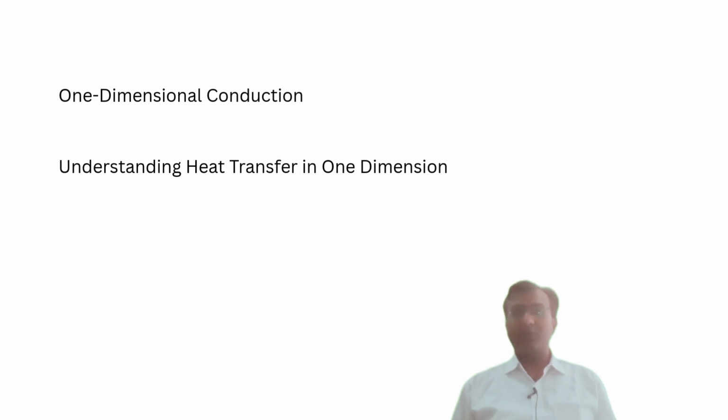Today, we will explore the principles governing one-dimensional conduction, starting with Fourier's law, which quantifies heat flow. We will also cover the assumptions that simplify our calculation, the heat equation, and practical applications like heat transfer in walls or pipes. By the end of this lecture, you will understand how to analyze conduction in simple geometries and apply these principles to real-world engineering challenges.